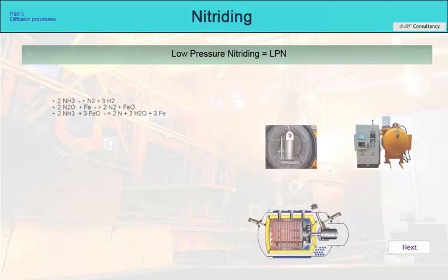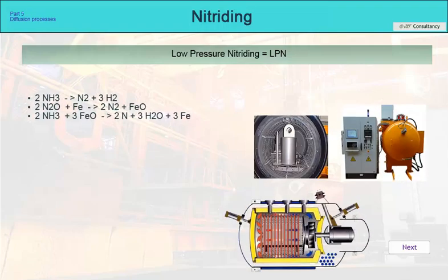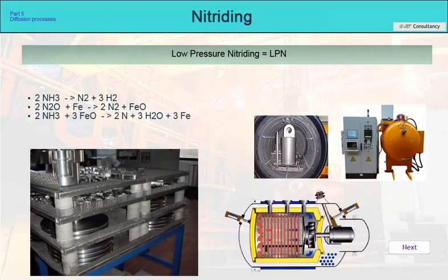Another nitriding process is the so-called low-pressure nitriding. It is a technology supplied by the Force BMI company from Lyon, which is in fact also nitriding in gas, although at a total pressure of only 300 to 400 millibar, equivalent to 30 to 40% atmospheric pressure. The low-pressure nitriding process is implemented directly into a vacuum tempering furnace with direct heating, and is adapted to work with gases such as ammonia, dinitrogen monoxide, and nitrogen at the above pressure.